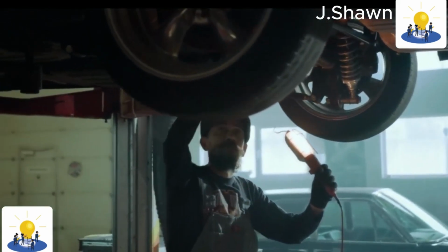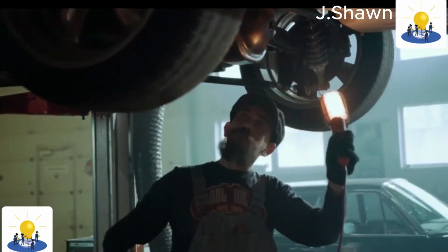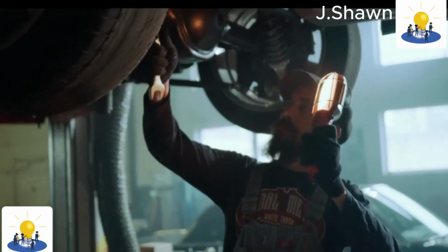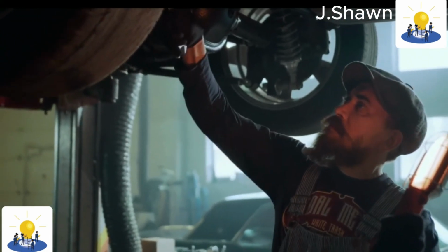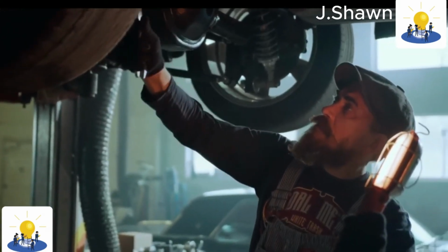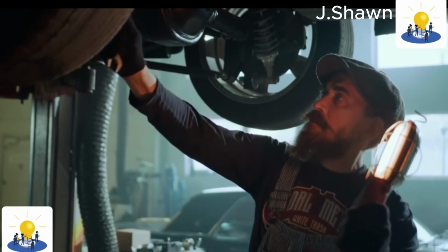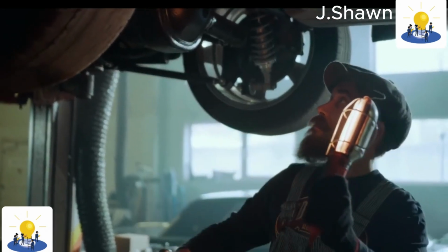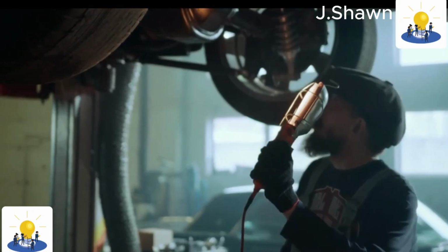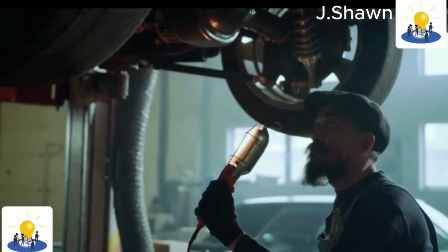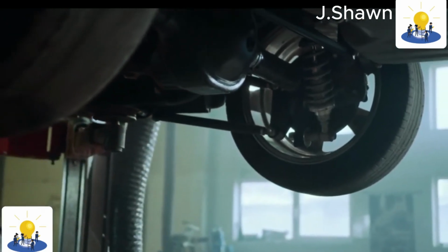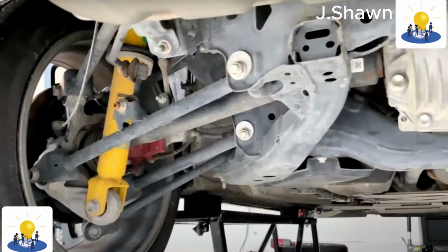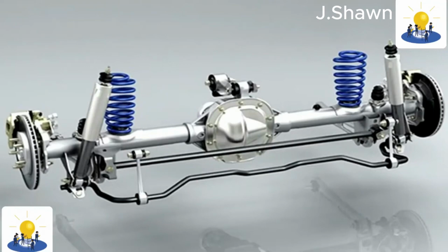The twist beam rear suspension is a similar suspension design, however its beam axle is able to twist, thereby functioning as an anti-roll bar to control the roll motion of the body, and is considered to be a semi-independent suspension design. A live axle is a type of beam axle in which the shaft, or commonly, shafts connected to move as a single unit, also transmits power to the wheels. A beam axle that does not also transmit power is sometimes called a dead axle. While typically used in vehicles with Hotchkiss drive, this suspension system can also be used with other types of power transmission.